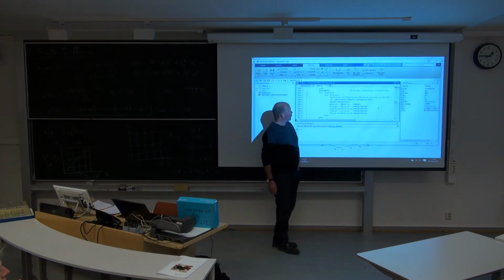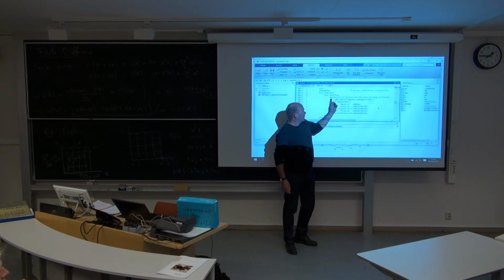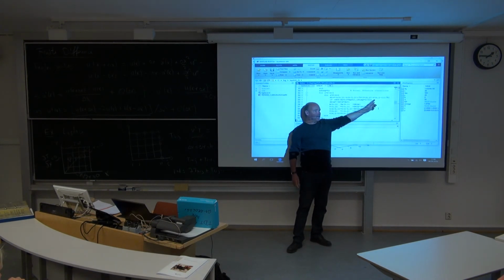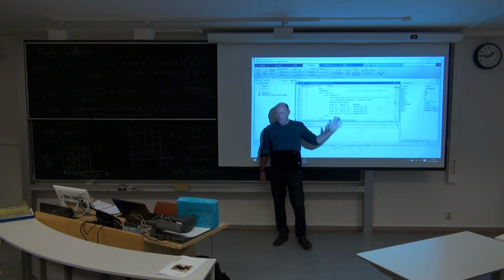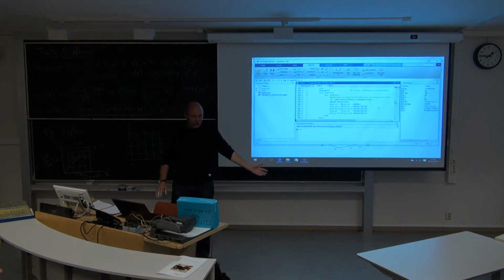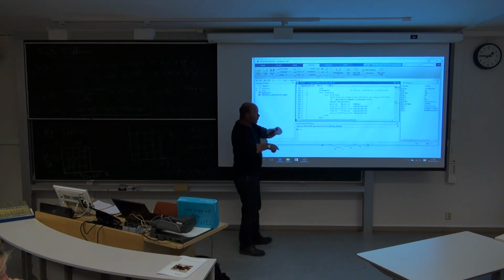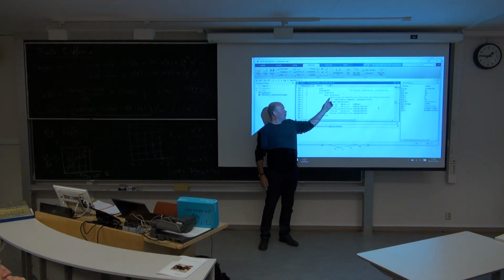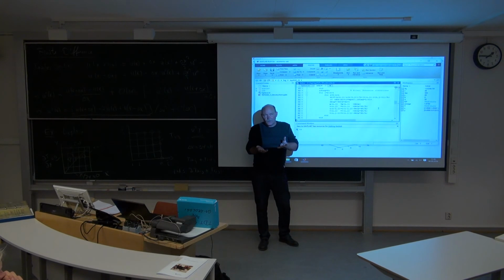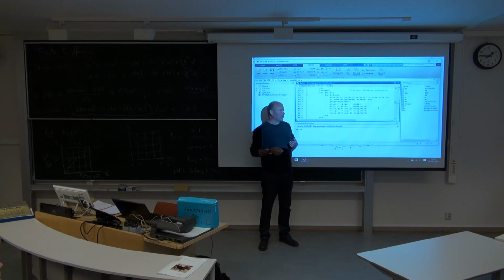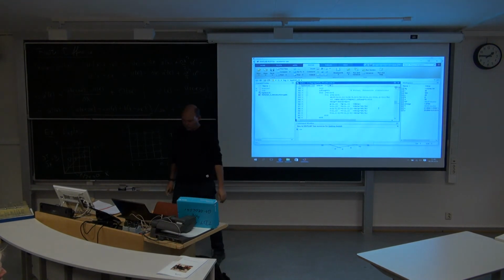And what we have also calculated here is the divergence. And this is something neat. You calculate the divergence of the velocity field. Because here we know this divergence has to be 0 if it's to be an incompressible flow, as it should. So in this algorithm, we can actually monitor for every iteration what is the divergence now, what's the maximum divergence. And if it's too big, different from 0, then we must iterate further. We need a more accurate solution. But then at least we have a physical argument for when we should stop.